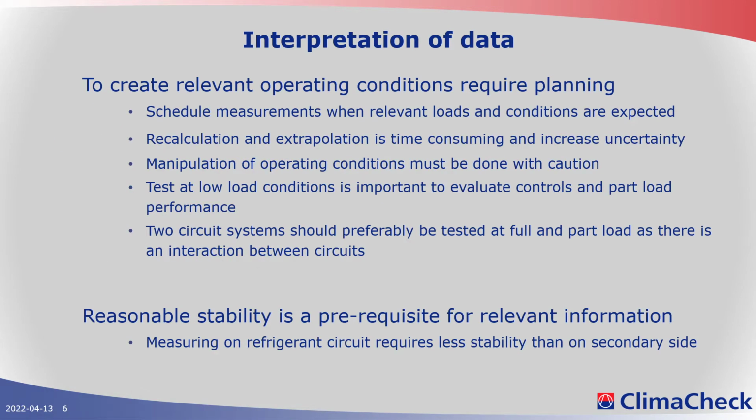And then a traditional maintenance visit might have started with the machine not running. You're coming out for an air conditioning system, early spring, it's only 10 degrees outside, and there's no load. So then you would have started the chiller, but in reality you will not know if it works correctly, because it will just change the temperature too quickly. So you don't get any stable operation.